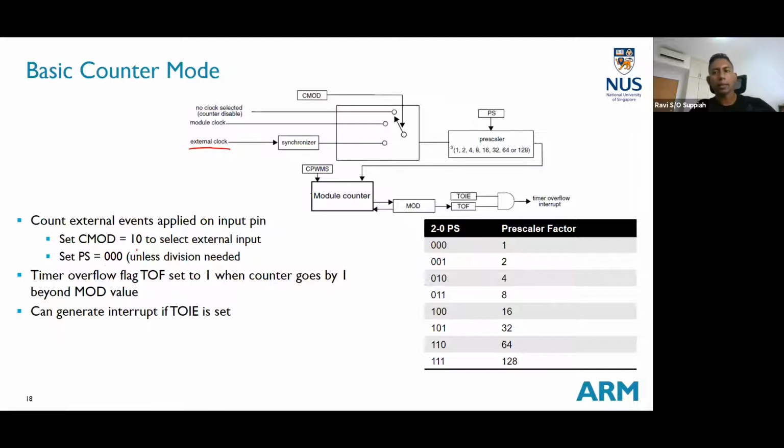All right, so one example is, if you want to connect encoders to your motor and you want to keep track of the count of your encoders, you can use timers also to do it. Of course, another way is you can also connect it to GPIO interrupts, and whenever that interrupt is triggered, you can keep track of the count. Okay, so there are different ways in which you can design a system, correct, depending on what is available and what approach you want to take.